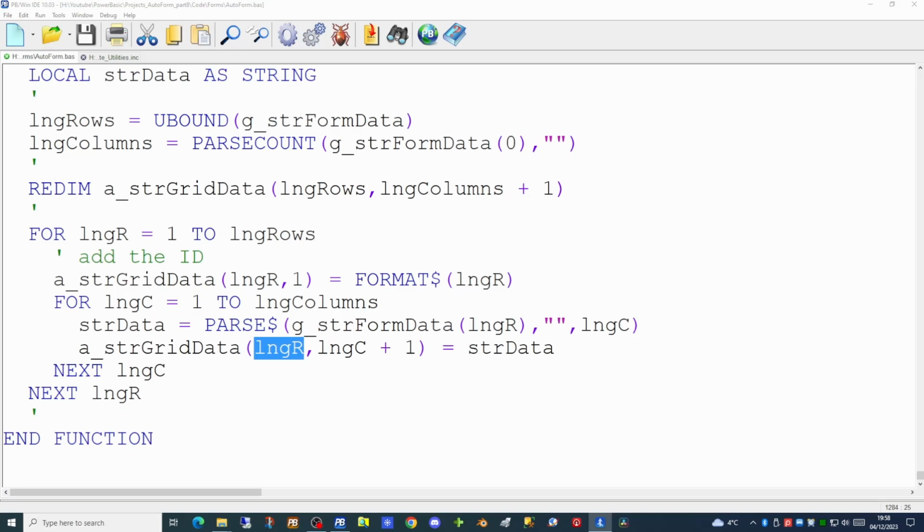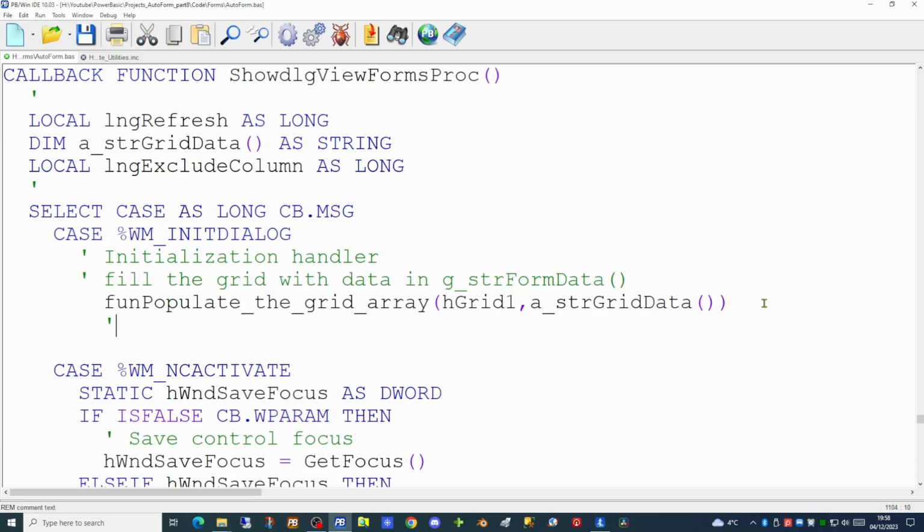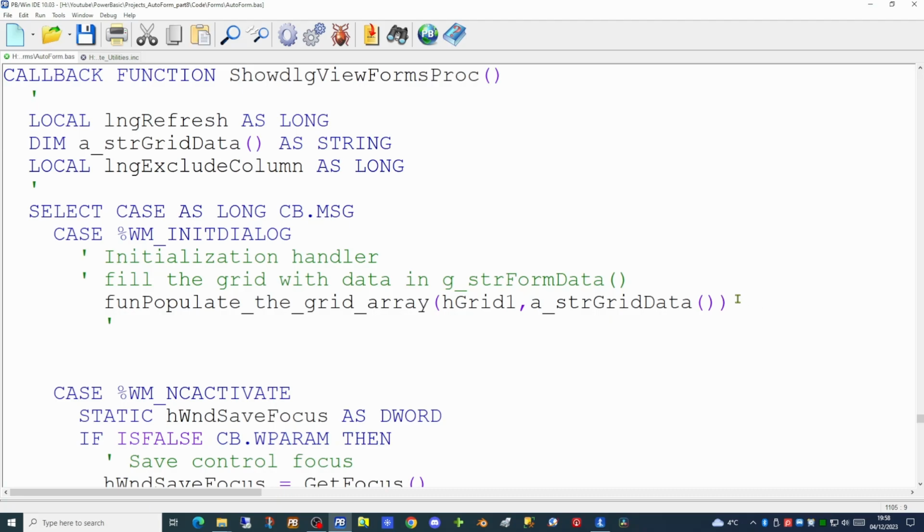So since this function will populate a two-dimensional array, how do we put that two-dimensional array directly into our grid on screen? Immediately after that new function is called, we're going to use one of MyLittleGrid's own functions, the mlg_put_ex command.